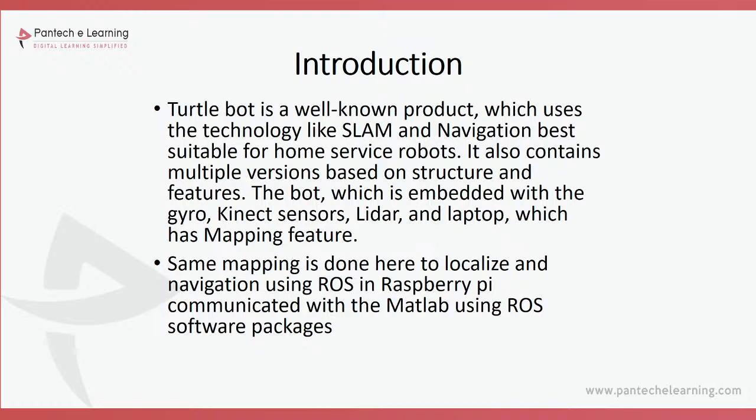Based on that light, it rotates in a 360-degree format, passing out light. Wherever the light hits and is received back, the detection range is calculated, and therefore it is able to obtain the distance and at the same time map. That mapping creates its own distance information and determines which path it should move along to avoid collision. These functions are what we will be able to implement inside this SLAM robot.